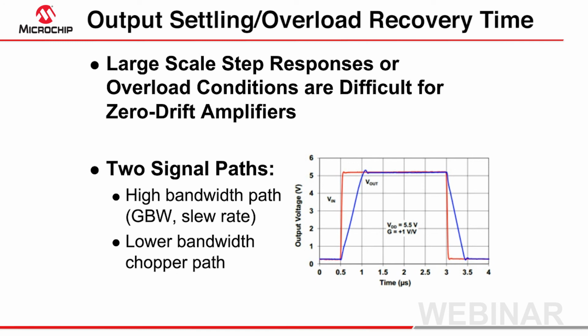Overdrive recovery is a similar scenario, except that the amplifier has to first return to within its linear range of operation, which usually takes some additional time. The total overload recovery time can therefore reach into the hundreds of microseconds.